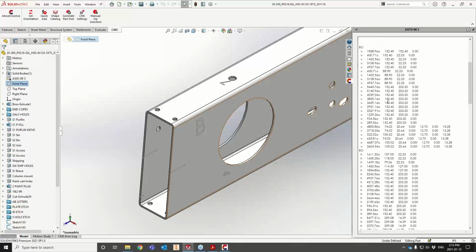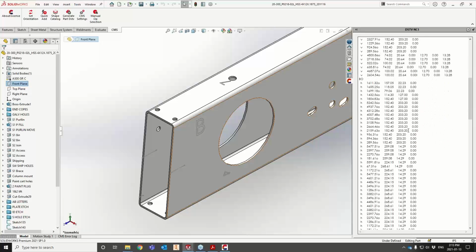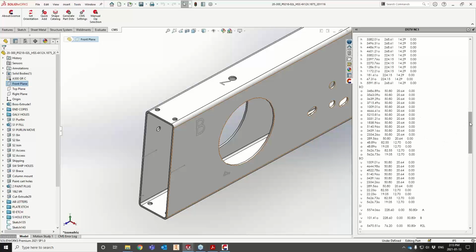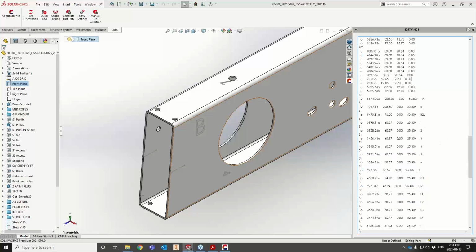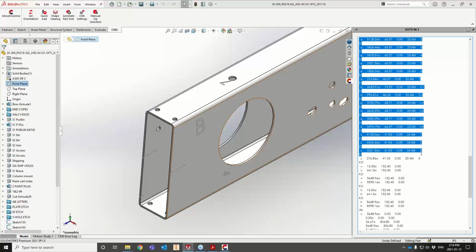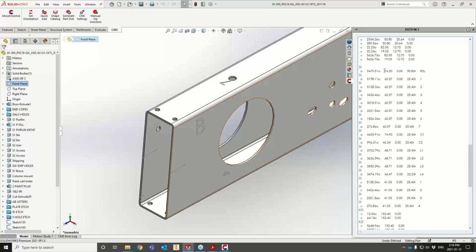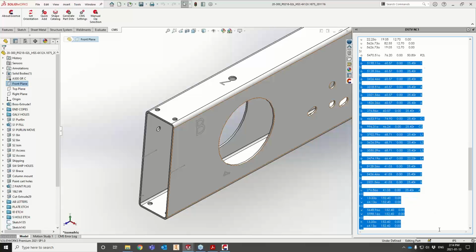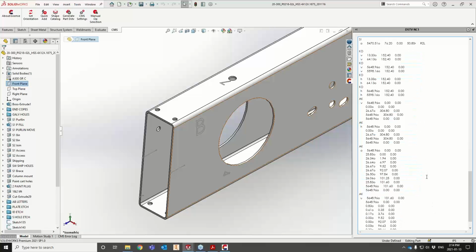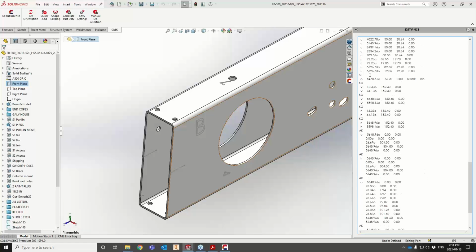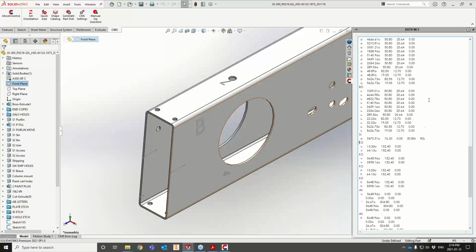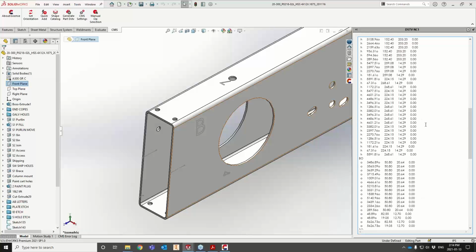And this NC1 Viewer window is pretty editable as well. So let's say your machine does not want to read your text stenciling block. You can just get rid of that. Let's say I just want to keep that one block just for visual purposes here. Let's say I want to keep this too. So I can just delete anything that I want from here as well. And I just kept only one text stenciling just to show you that you can also do some quick changes.